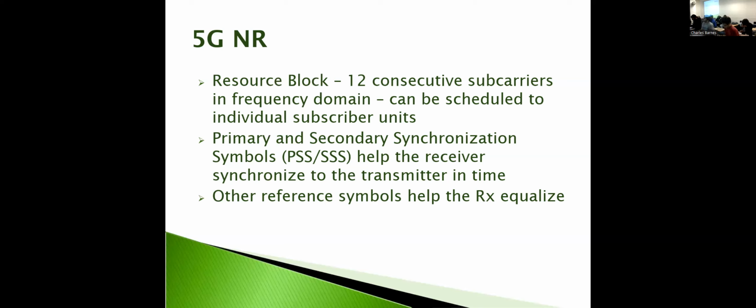So the base station is going to make a transmission, and it's going to send out a frame of data, and that's going to include, let's see, 10 times 14, 120, maybe 100 or so OFDM symbols, right? Each of those OFDM symbols might have 3,000 subcarriers in it that have data in it, right?